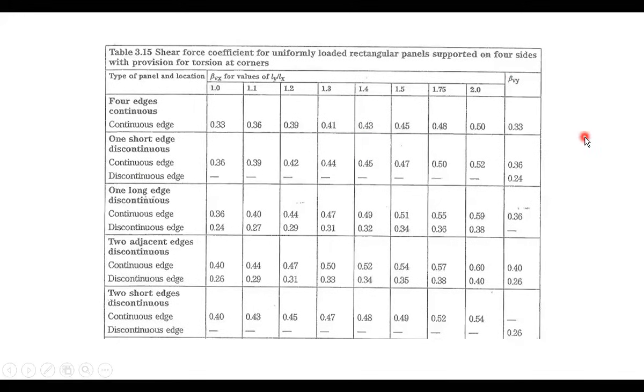For the moment, you have to design at different places, because each moment will give you a different value of reinforcement, tensile reinforcement, and you will have different values of reinforcement at different places or at different positions of bending moment.